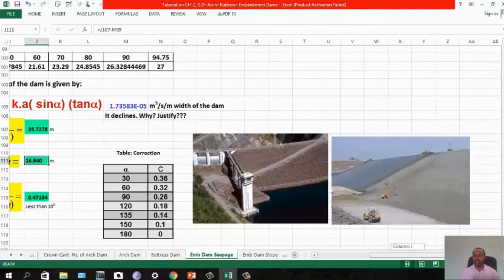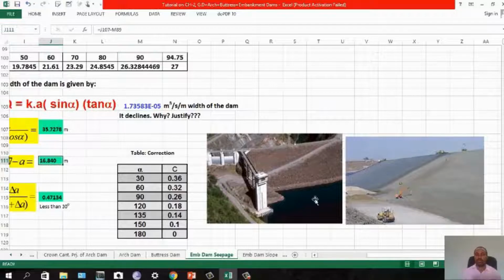So these are sample embankment dams photo. You can see just this is walkway. Then you have tower intake. Then if you have some inspection or maintenance, you go through walkway and enter to the intake tower, then you can maintain it. So you can see again, the spillway is separate. So you cannot construct spillway in the body of the dam. Since it is an embankment dam, erosion may be high, so separate spillway should be constructed for embankment.